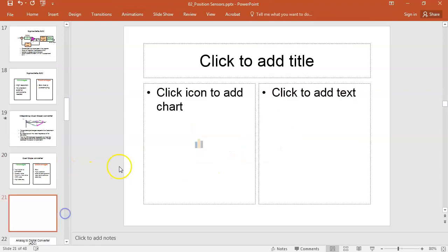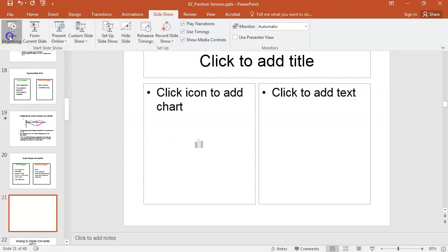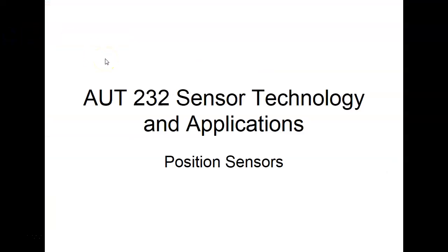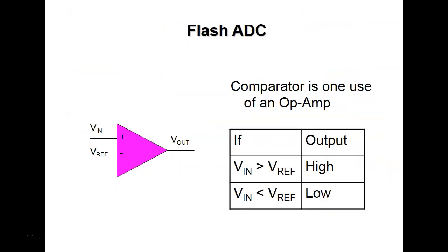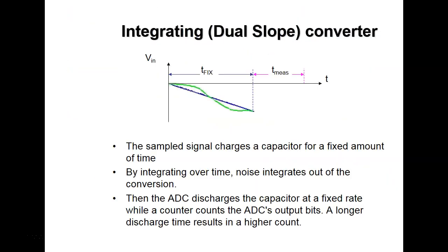Let me put up a new slide so I can get this. So this is a good problem. I've got a pot, and I want 10 volts right there because I'm going to bring this into the input of my PLC. And all I've got up here is a 24 volt supply.